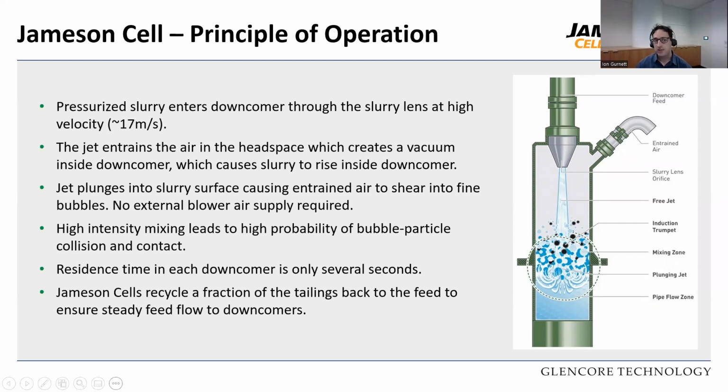This high intensity mixing creates a really high probability of bubble particle contact and collision. And it's this forced contact that allows us to size these away from residence time. We only need to look at the grade recovery curve and volumetric flow. Residence time, if you want to be exact, is probably only a few seconds in these downcomers. But that's all we need because we've already enforced that particle bubble contact.